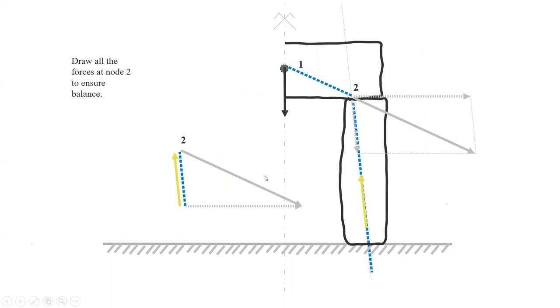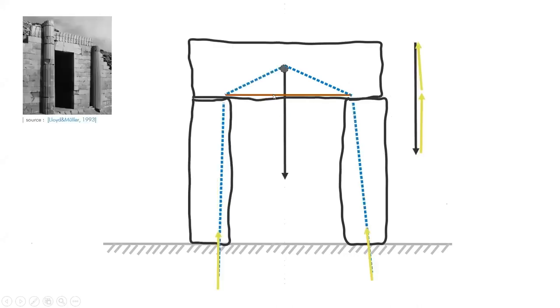You can assess its value using again a triangle of forces, and it will demonstrate that since you're not able to push here toward the node, you will need an internal force appearing in the system. So this demonstrates what's happening in the system. And indeed, you have the traction force that could lead to a break in an arch as here.